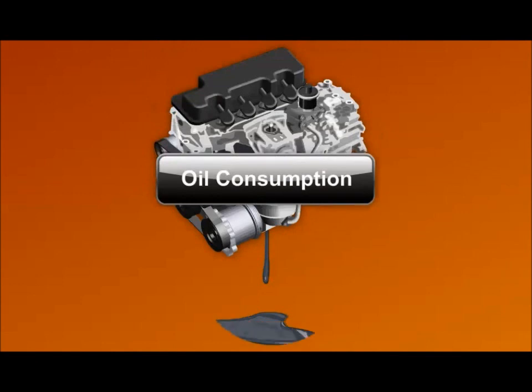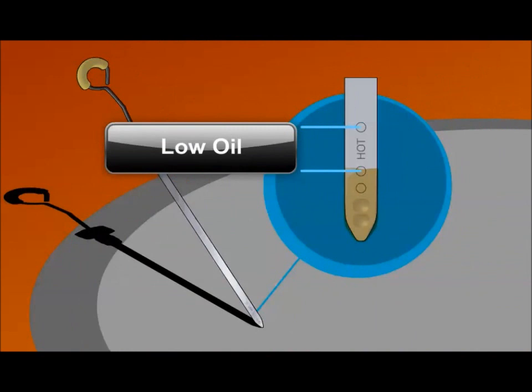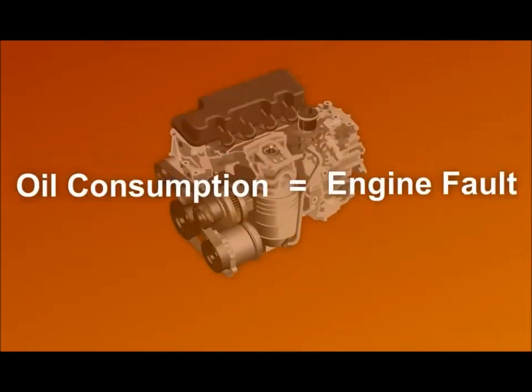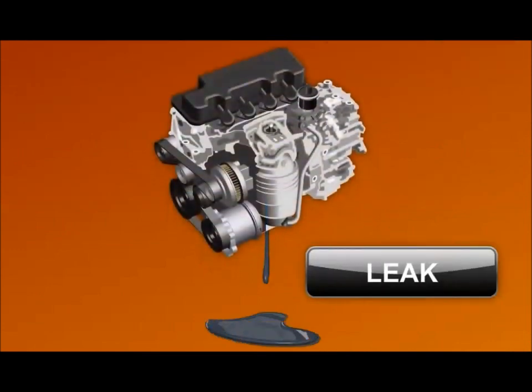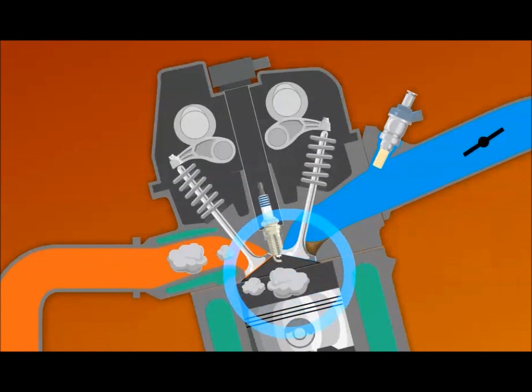Unlike drivability and vibration faults, oil consumption problems have a single symptom: oil loss. Any engine with an oil consumption problem has a mechanical fault. These faults include simple oil leaks from seals or gaskets, or an internal fault that allows oil into the combustion chamber.